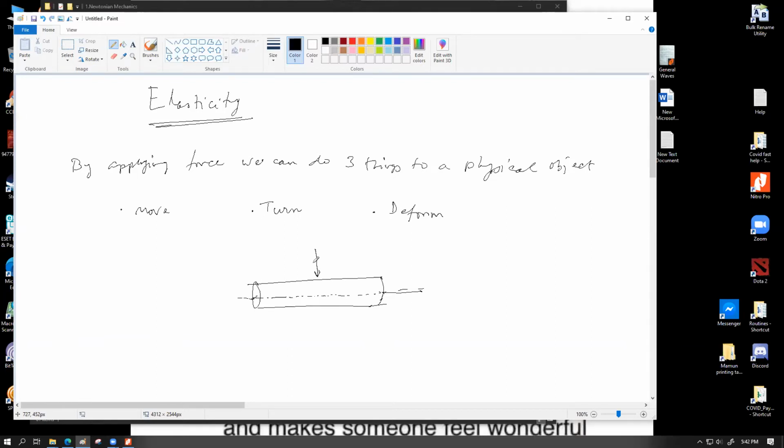Bend and twist are not the same thing. You have to understand this. Whenever we apply some load onto a long object, if we apply some lateral load, something like this, as is shown in the figure, this object is going to try to bend, which means these two sides will pretty much stay in the same position, but we're going to have a bit of a curve at the middle going downwards. So that's what we call a bend type of movement. So that is what we call lateral load.